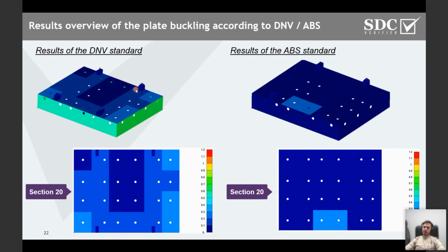You can see that there is possibility to preview the results in a very easy way. So to show all the utilization factor for your whole structure for certain sections. So I selected one section here and here, so I can easily show all the values here. Of course, you can also preview them with tables just for every separate element to show separate utilization factor and all the calculation details.